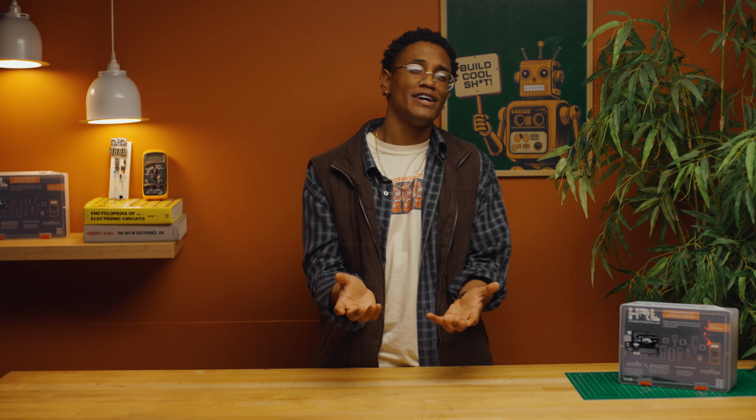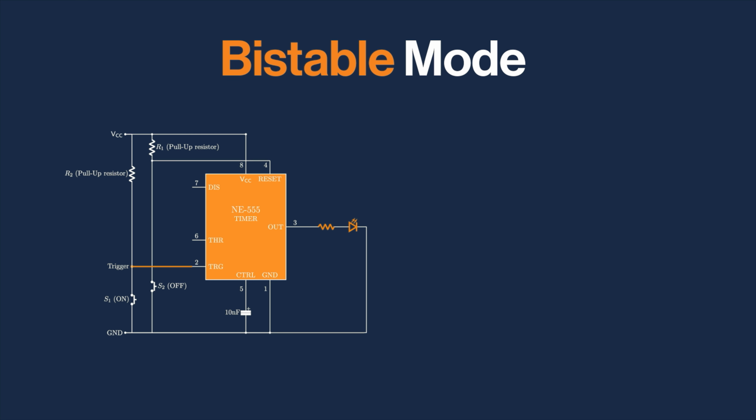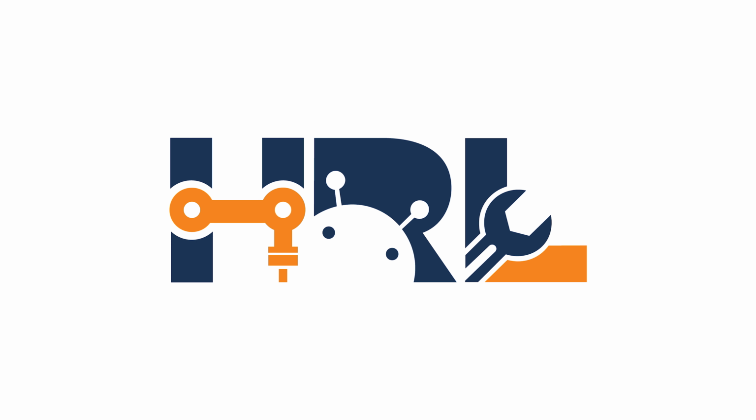Third, and finally, we have bistable mode or toggle mode. And this one acts like a flip-flop. It stays on or off until another input tells it to switch. This one has no automatic switching. It waits for your signal to switch again. A clear example of this one is a touch-sensitive switch that toggles an LED on or off depending on when you press it. So how do I know all this?